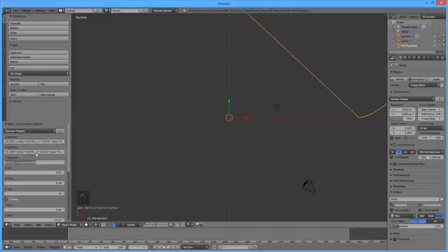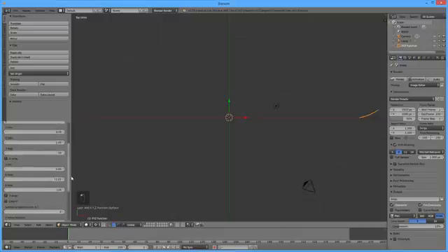Enter 0 for the Z equation. U-min should be 0 and U-max should be 1. Enter 10 for U-step and uncheck the U-wrap box. The V parameter is not used, so enter 0 for V-min and V-max, and 1 for V-step.